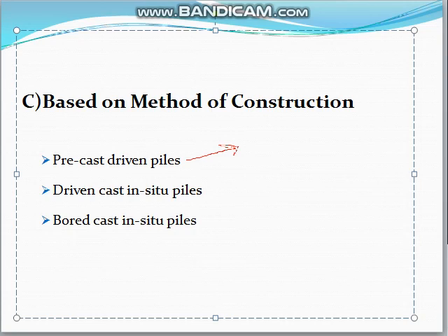Another one is the driven cast in situ piles. Piles are formed by driving a casing with a closed end into the soil. The casing is filled with reinforcement like steel and concrete. The casing may or may not be withdrawn.